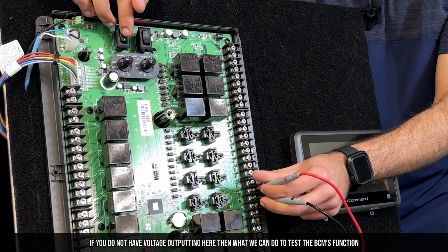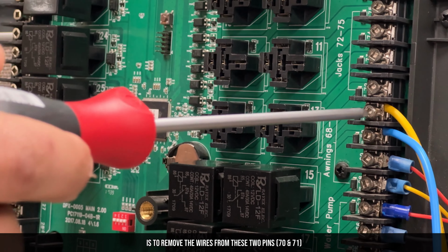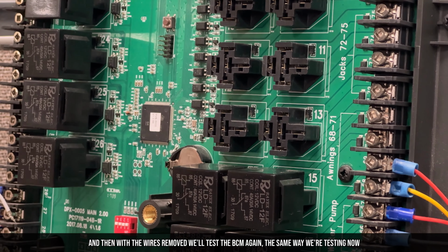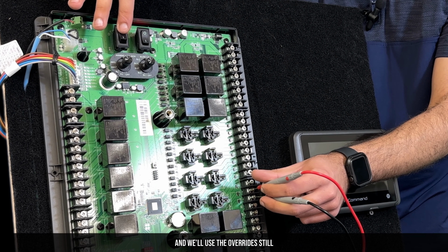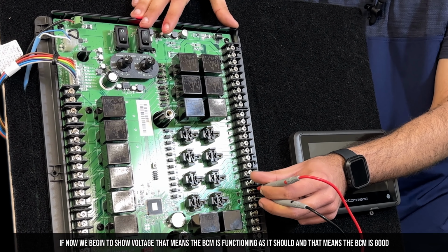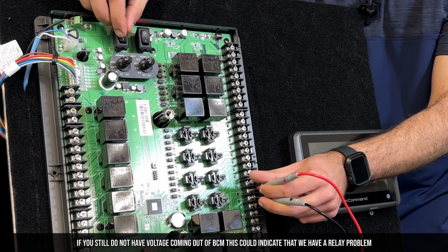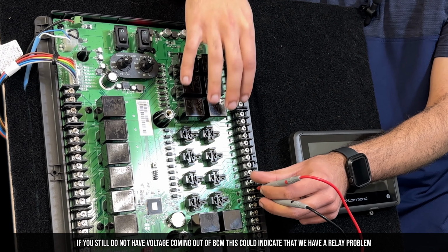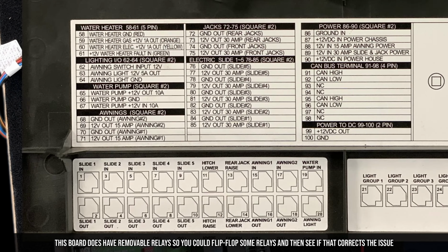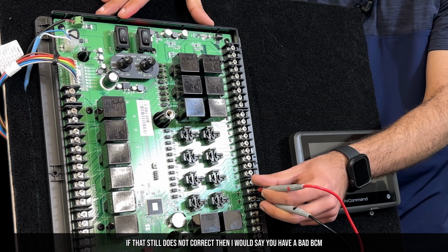If you do not have voltage outputting here, then what we can do to test the BCM's function is to remove the wires from these 2 pins. And then with the wires removed, we'll test the BCM again, the same way we're testing now, and we'll use the override still. And if now we begin to show voltage, that means the BCM is functioning as it should. And that means the BCM is good. If you still do not have voltage coming out, this could indicate that we do have a relay problem. Now this board does have removable relays, so you could flip-flop some relays and then see if that corrects the issue. And if that still does not correct it, then I would say you have a bad BCM.